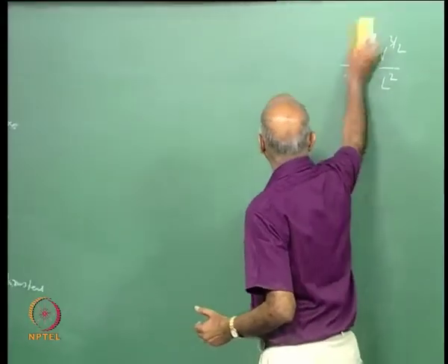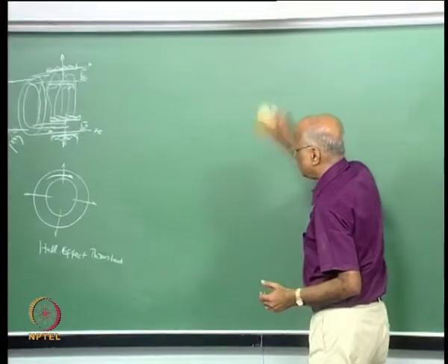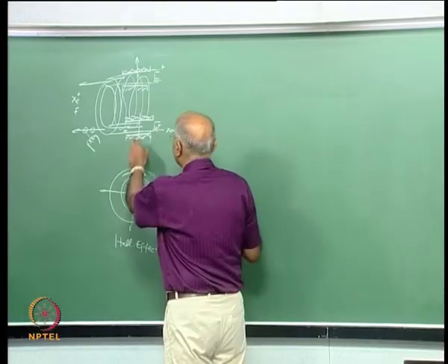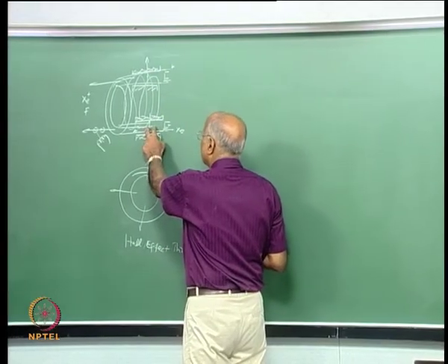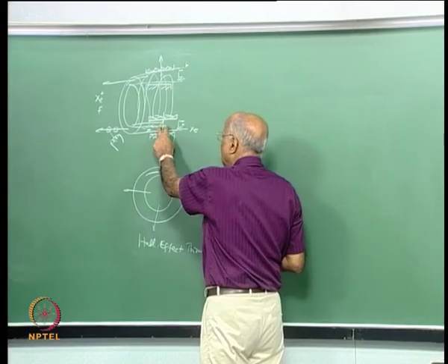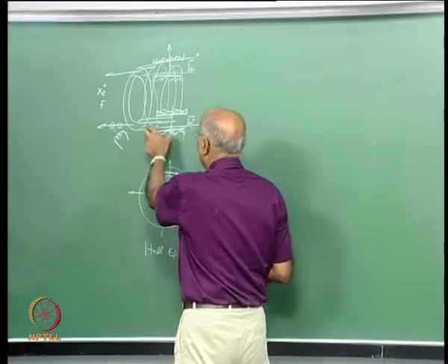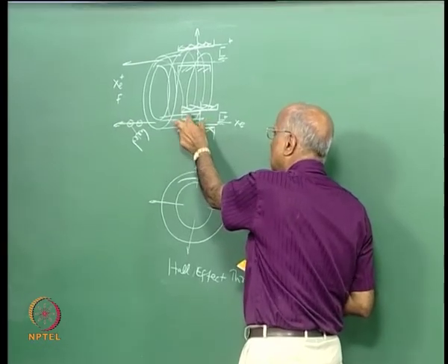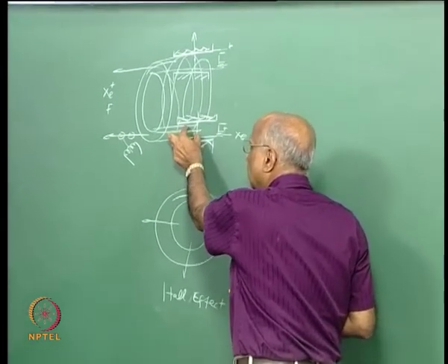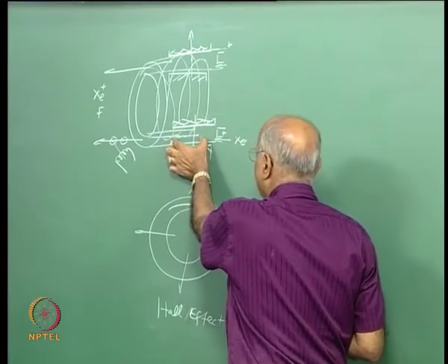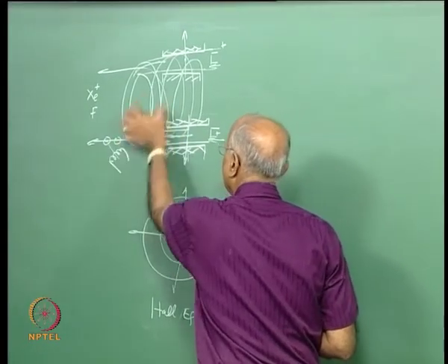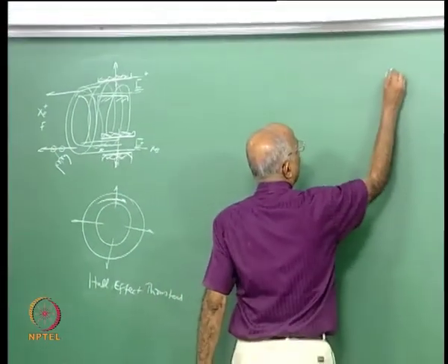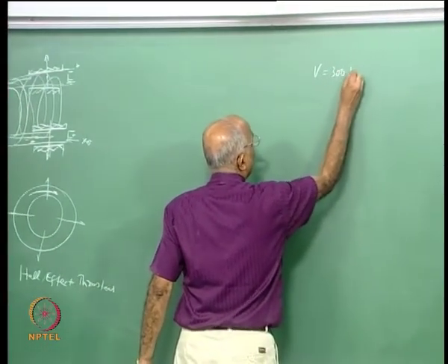Therefore, all we will say is Hall effect thrusters make use of the spiraling effect of the electrons which collide, and since the spiraling effect is used, you do not have things like Child's law limiting the beam current. This is essentially a plasma consisting of a lot of neutral gas. You do not have the problem of any sputtering here, and it is an easy thing to use, and I use a low voltage of around 300 volts, I am sorry, not kilovolts.